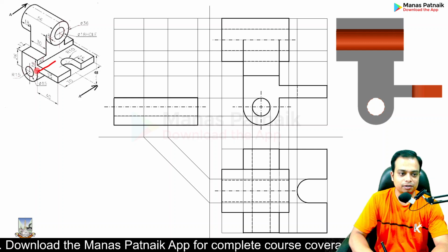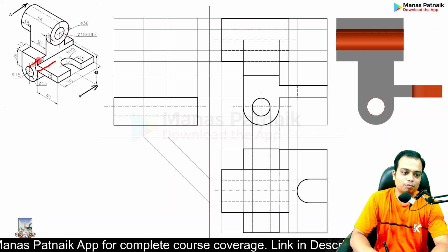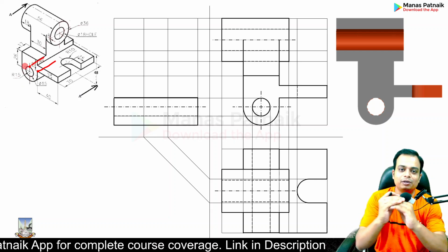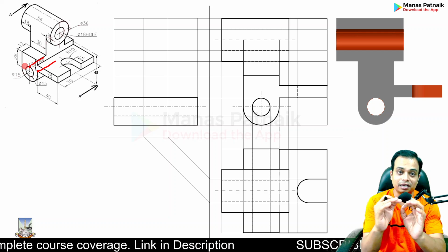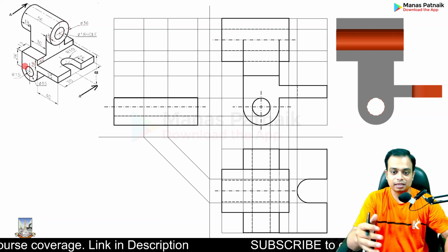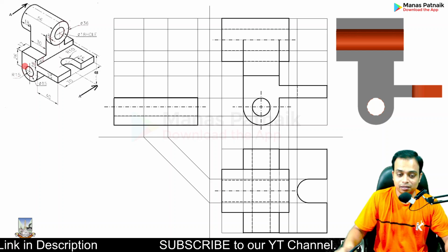There is an edge through this very point. That edge and the hidden line from over here are extremely close to each other. There is a difference of 0.5 millimeters only, right? So the thickness actually gets overlapped with it. That is the reason. When you make it with pencil, these things may not happen.